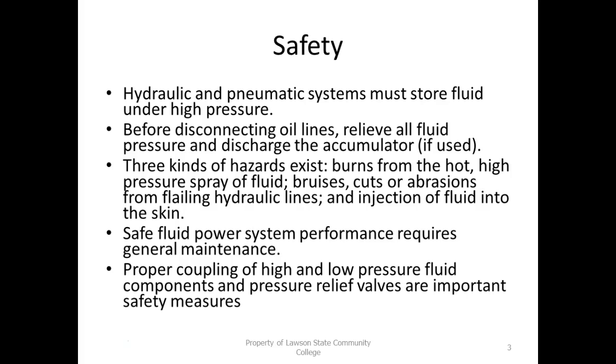What we do in pneumatic systems sometimes is either buy self-lubricating valves, which are available, or put an oiler in the system, which basically squirts a little bit of oil into the air to keep everything lubricated. Unfortunately, on two of our robots, we don't have that, and they're not self-lubricating valves. So every once in a while it won't work, and we literally have to take the valves apart and oil them. We do have the lubricators; we just haven't had the chance to install them in the airline.